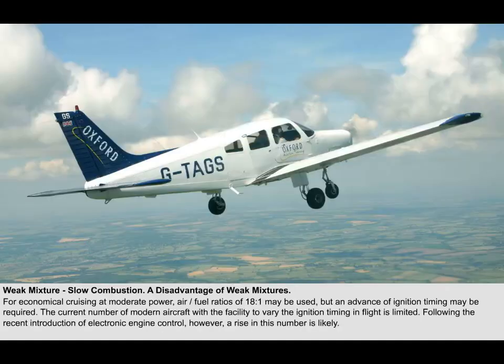For economical cruising at moderate power, air-fuel ratios of 18:1 may be used, an advance in the ignition timing being necessary to allow for the slower rate of combustion. The current number of modern aircraft with the facility to vary the ignition timing in flight is limited. However, following the recent introduction of electronic engine control, a rise in this number is likely.